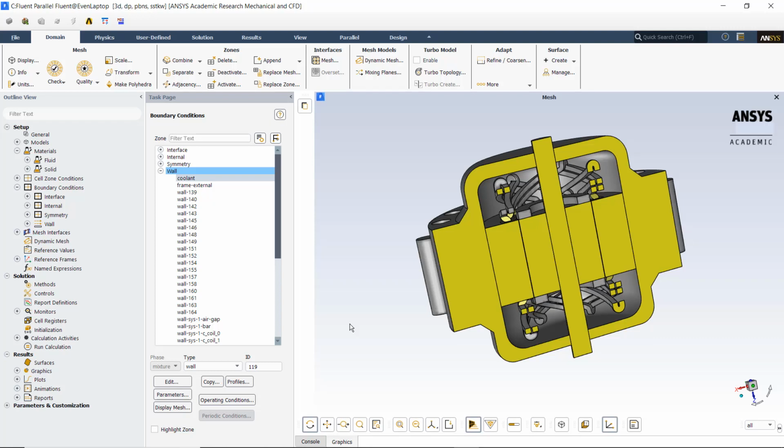You may also solve the natural convection of air in this enclosed region, for which you need to create a volumetric mesh for the void region as well. Another option is to treat this region same as what we did for the gap region between rotor and stator, meaning that we take into account only the conductive heat transfer of air. In this demo, I assume that all these walls are adiabatic, which is a conservative assumption.